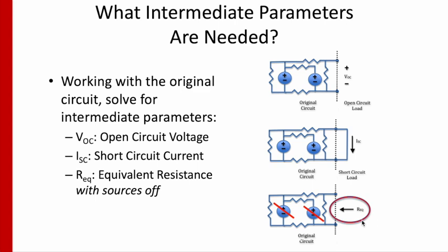Okay, lastly, REQ, the equivalent resistance seen looking into the port. A couple quick comments here. First of all, this is with the sources off. So we deactivate the sources, the internal sources that are in this original circuit.